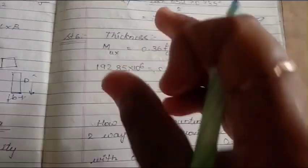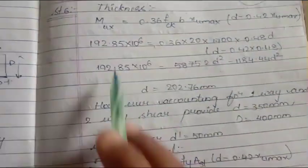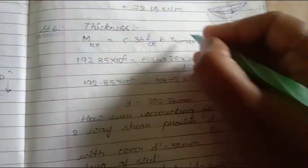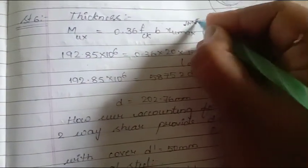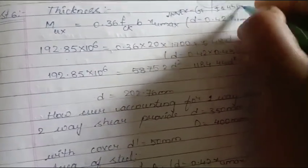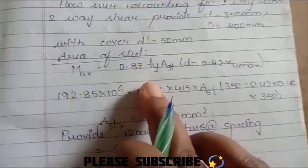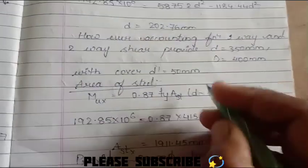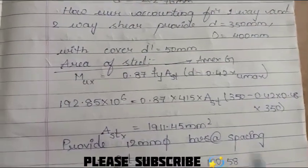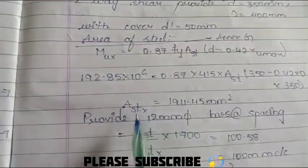So that is why we will be considering it for the greater moment. Whatever the greater of the MUX and MUY value we have got, take that one over here. Calculate the thickness using this formula. Don't forget, this is very important. It is provided in the annex D of IS 456 2000. Next, area of steel. This is the formula. Even this is provided in the annex D. Substitute everything in this, you'll be getting AST.